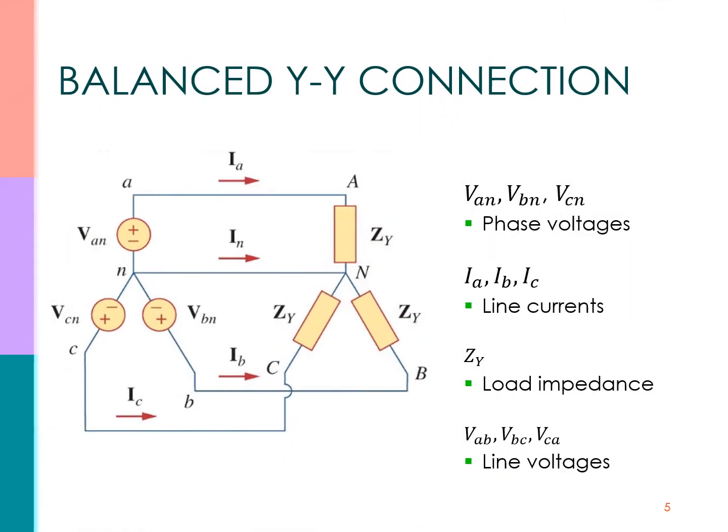We begin with these balanced Y systems, because any balanced three-phase system can be reduced to an equivalent Y system. Therefore, analysis of this system should be regarded as the key to solving all balanced three-phase systems. A balanced Y system is a three-phase system with a balanced Y connected load and a balanced Y connected source.